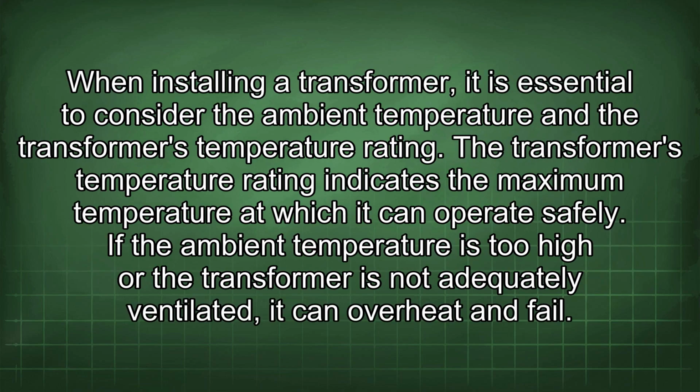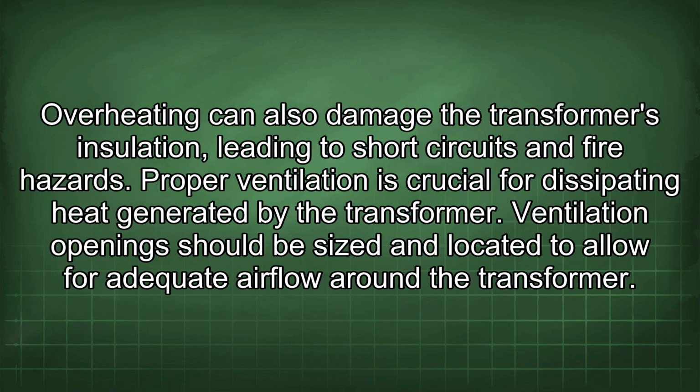When installing a transformer, it is essential to consider the ambient temperature and the transformer's temperature rating. The transformer's temperature rating indicates the maximum temperature at which it can operate safely. If the ambient temperature is too high or the transformer is not adequately ventilated, it can overheat and fail. Overheating can also damage the transformer's insulation, leading to short circuits and fire hazards.